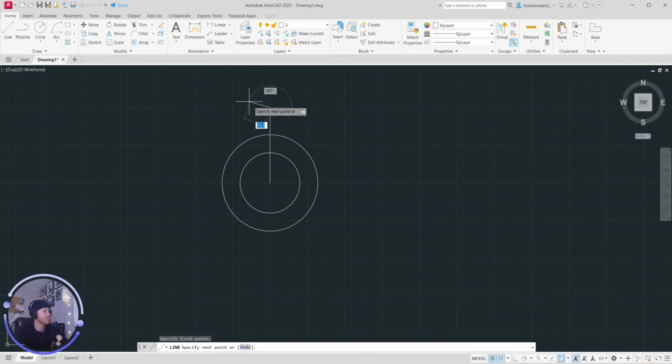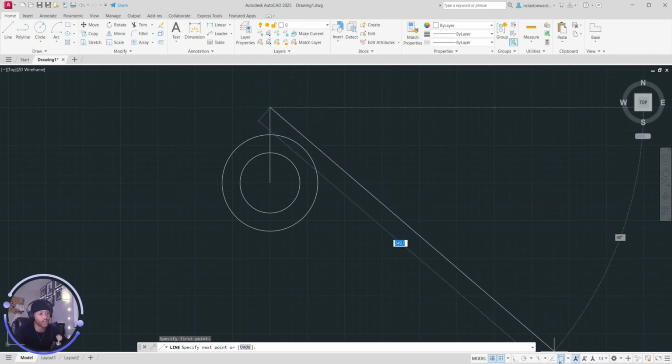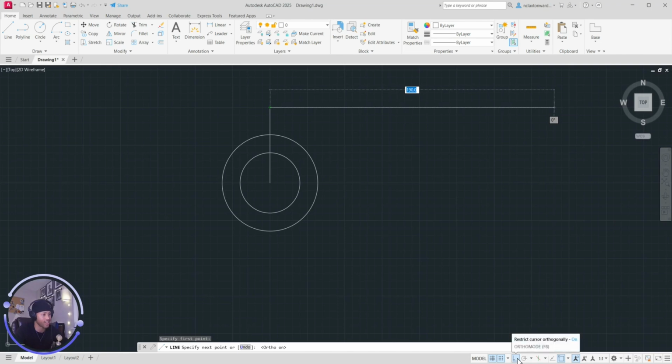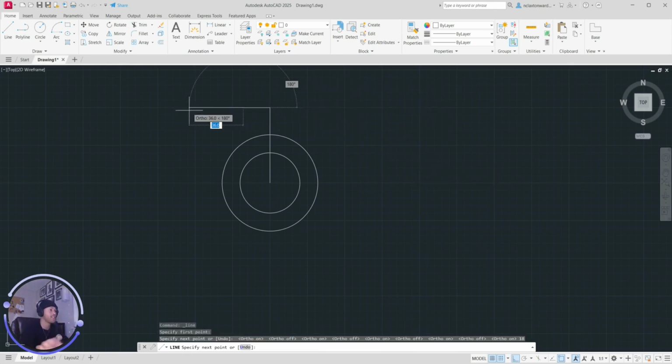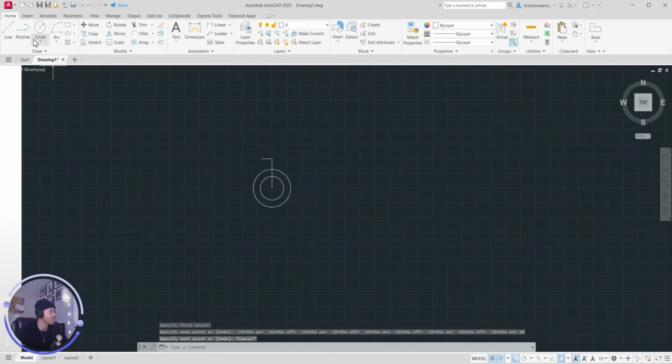And if you want it to only be in straight lines and you don't have to orient it always, just press F8, or you can press, I believe it's this guy down there. It's called ortho mode, but it tells you you can use F8. So I always just use F8. So I'm just tapping F8. F8, it's 18 across. Then we can start doing the circles.